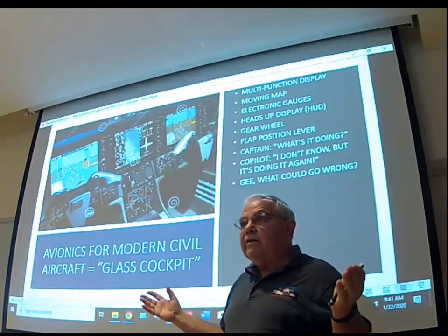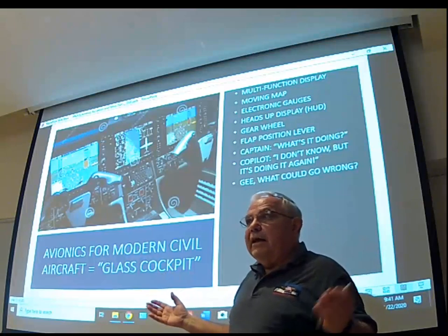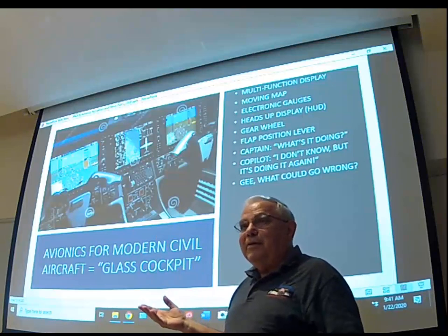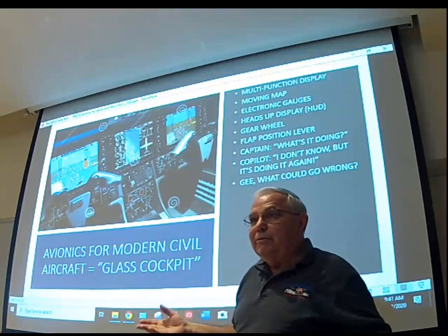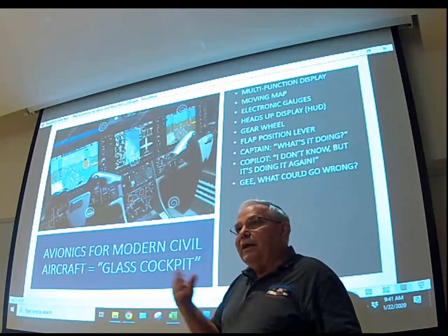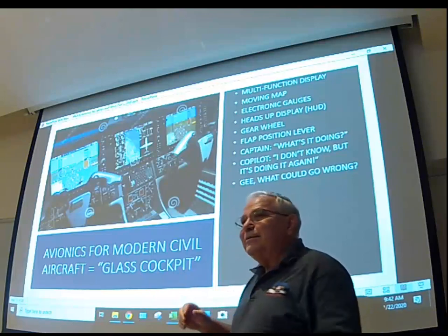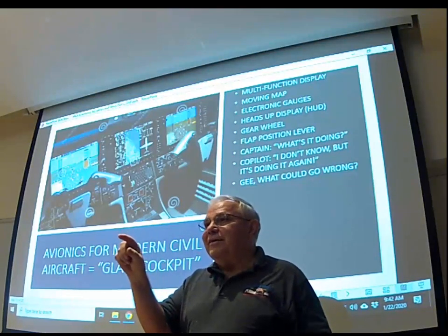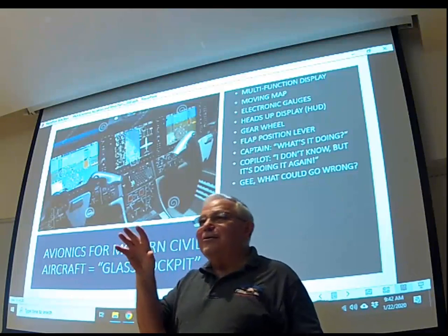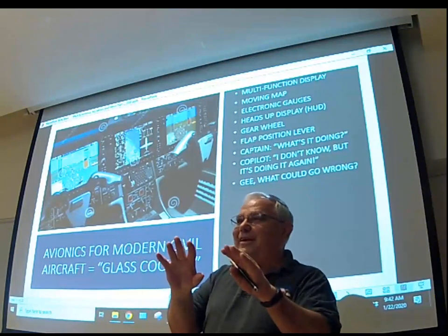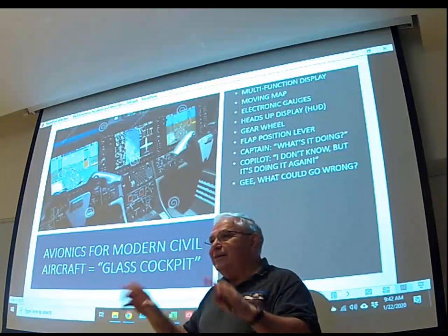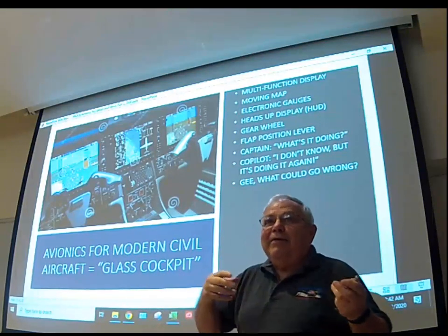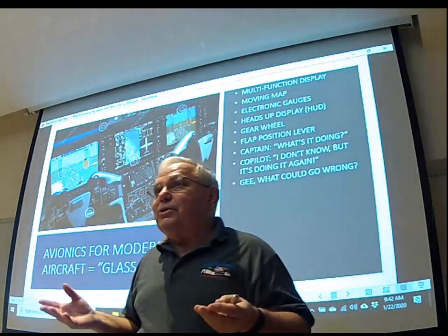Well, but now you have nothing. I had to go by the sound of the engine to judge what RPM I was at, right? I had no idea what my airspeed was. So I came back and landed, and when I'm taxiing in, I noticed that somehow I had hit the night button on the light. So the aircraft thought it was night out, and it dimmed the display. So it wasn't broken, it just had dimmed to the point where I thought it was out. But having experienced that kind of thing really gets your attention.